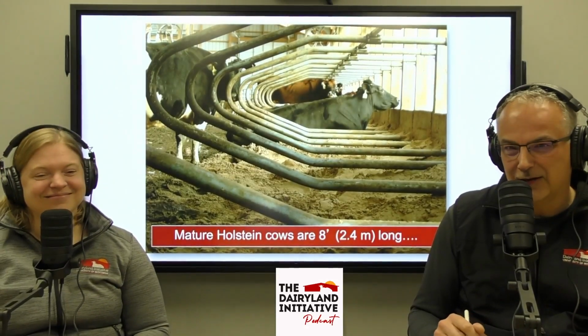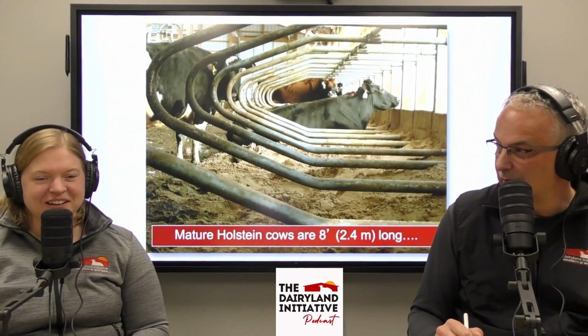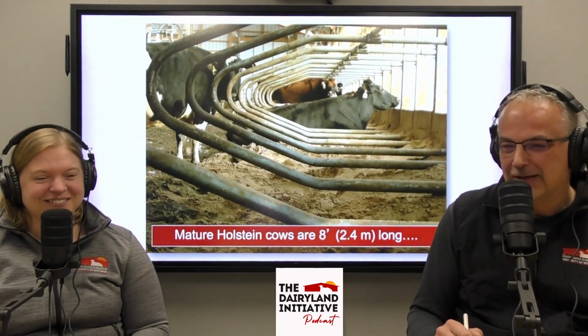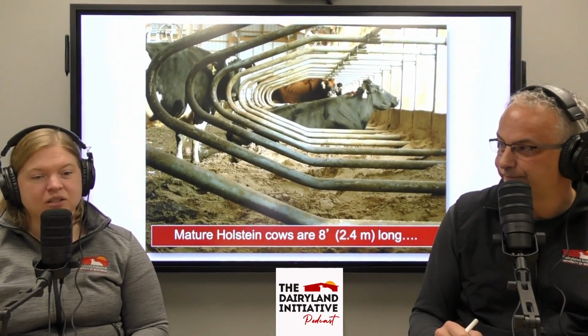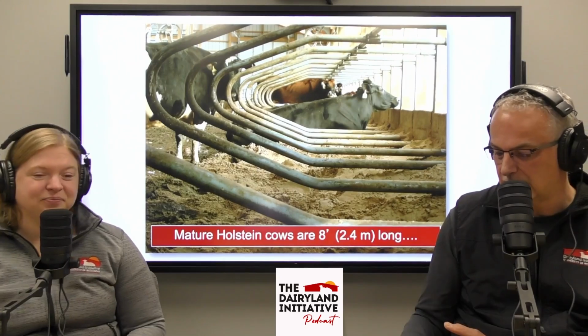This is a barn that I'm showing here with an 8-foot cow in an 8-foot stall. Wow, she's touching the sidewall. Shockingly, her nose is touching the sidewall when she's lying down. So that's a usable stall, provided she can lunge to the side, which she can in this scenario, because there's no obstruction to the side. But that's just not ideal, because again, when you lunge to the side, that's going to promote diagonal lying, dirtier stalls. And it does promote a bit of remodeling.